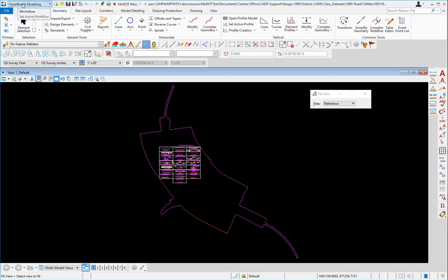First of all, everything in the vertical is going to be listed under this OpenRoads Modeling. So we can expand that out and open that up. Where we're going to be located inside of here is going to be the Geometry tab, and you should be able to see the ribbon now appear for that Geometry tab. Now this contains all for horizontal and vertical geometry. We're going to be working in the vertical area when we create these items, and I just kind of want to go over what's in the ribbon for vertical.